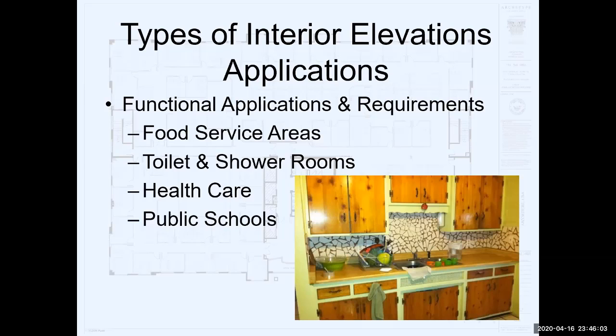But I think it's important to understand that the planning part of this requires a little bit of thought. How many elevations and how much space they're going to consume on a sheet and how they're grouped together is kind of important. So we want plans generally to go with elevations when we can put them together and where the sheet space provides. That means the person who's viewing the information can look at the plan and then look at the elevations at the same scale immediately adjacent on the sheet and have an easier time understanding all the parts and pieces.